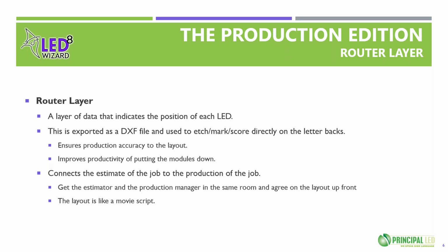Now, depending on your equipment, when I say mark or etch or score, this could be just a Z depth on your router bit. It could be a pen on your router. I've heard of people laser cutting the marks at a low power. I've seen for cabinets, shops plot out a pattern. Let's say you're mounting on acrylic, you put that pattern right under the acrylic, you see right through it, you see where the modules go. So there are a lot of different ways that you can utilize this, and some of it depends on your software, your equipment, and your workflow.